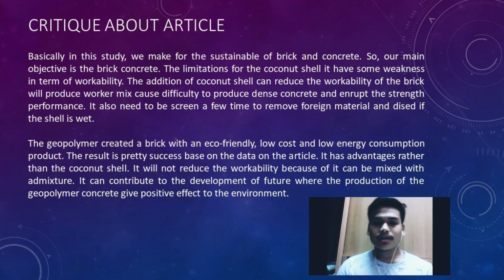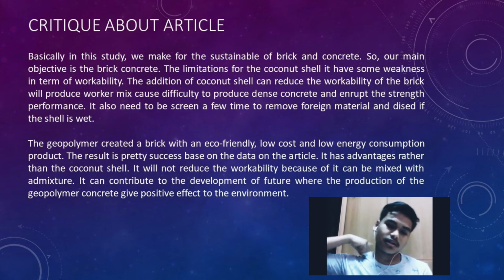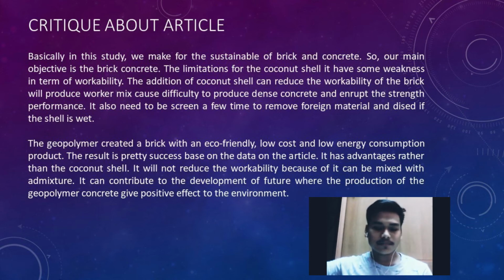There are some weaknesses that I noticed in the article on coconut shell as an aggregate. The coconut shell has some weakness in terms of workability. The addition of coconut shell can reduce the workability of the brick. And the brick will also produce a harsher mix that can cause difficulty in producing a dense concrete and interrupt the strength performance of the brick.